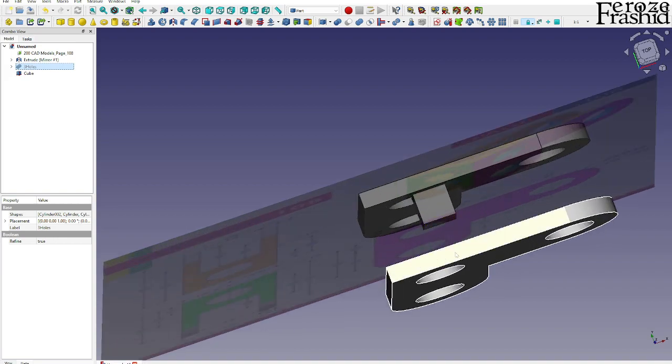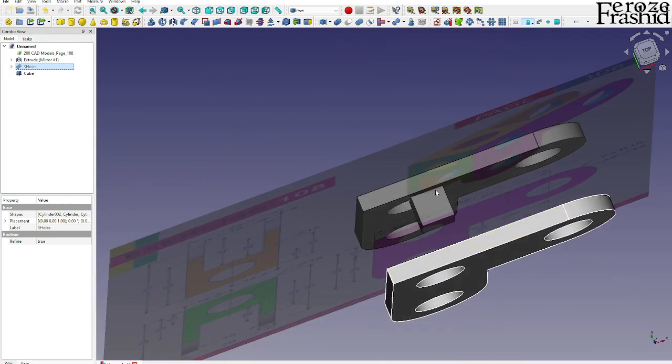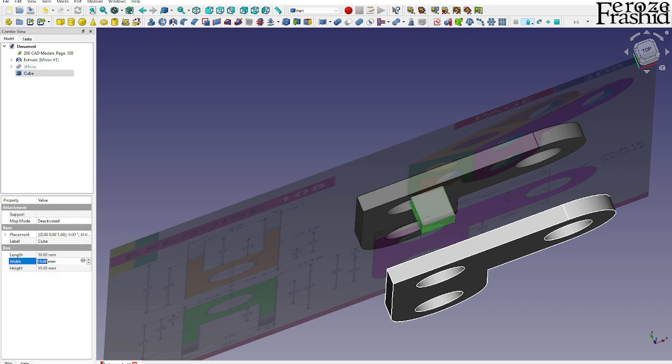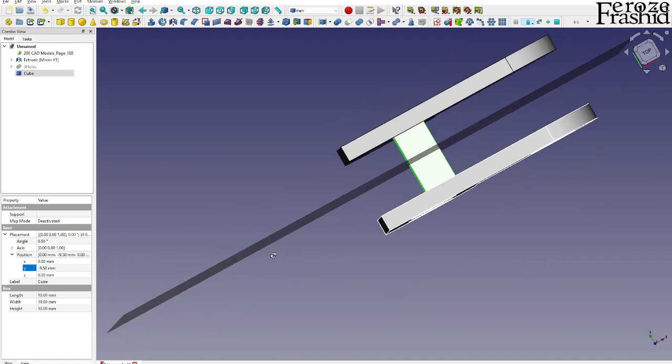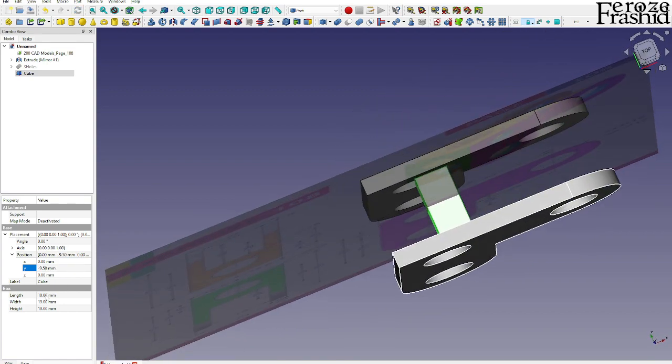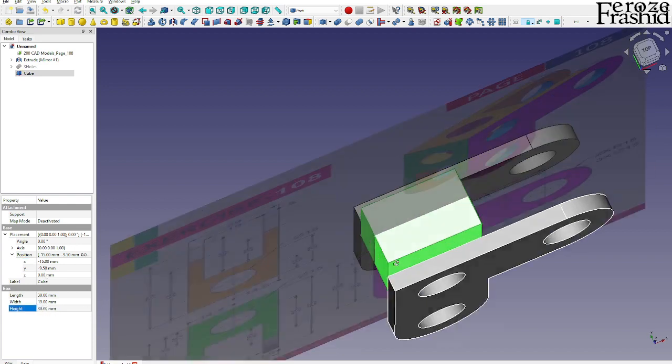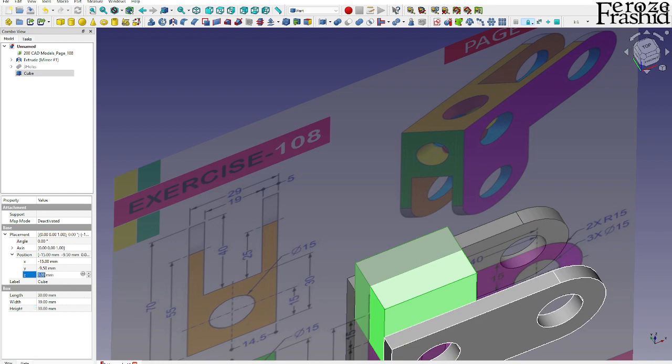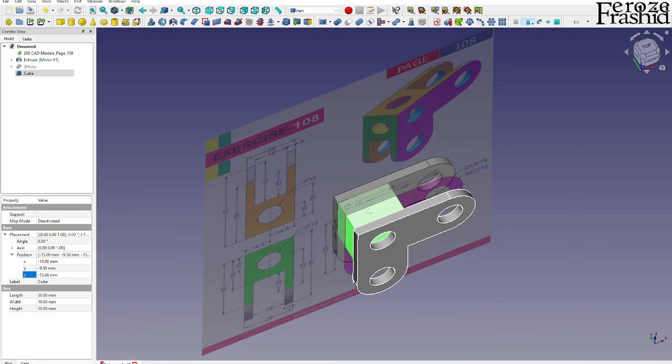So that cube will be spanning 19 millimeter, so spanning between these. So I'm gonna say the width it would be 19, but it went to the wrong side, so I'm gonna say on this one a minus 9.5. So that brings between these two, right? And length it would be 30, and we'll have to bring it minus 15 back, and height it would be 30, and we'll have to bring it down by 15, so that's like half the length.